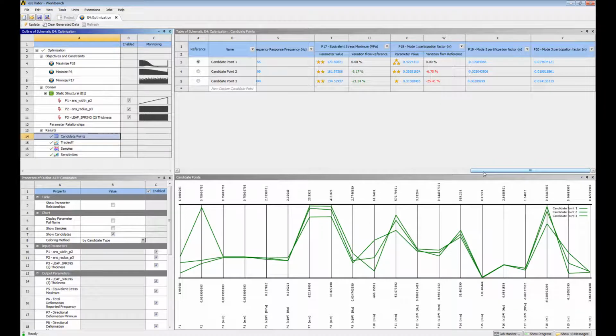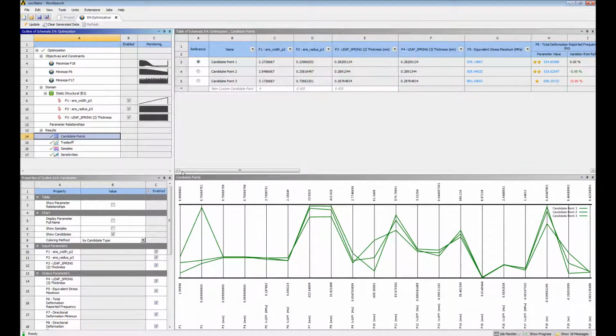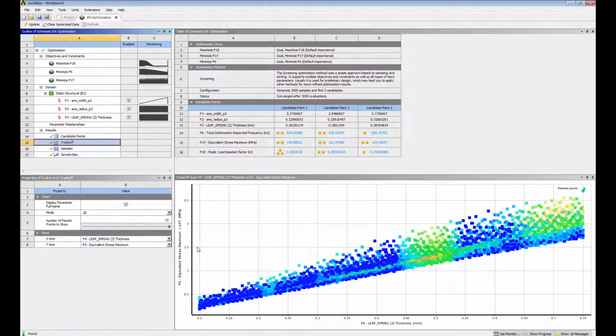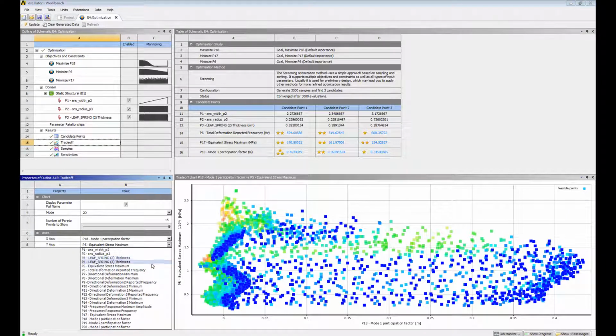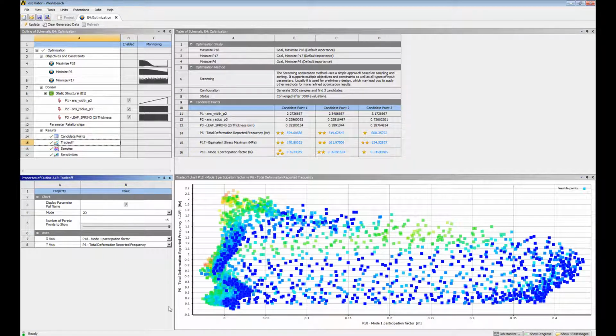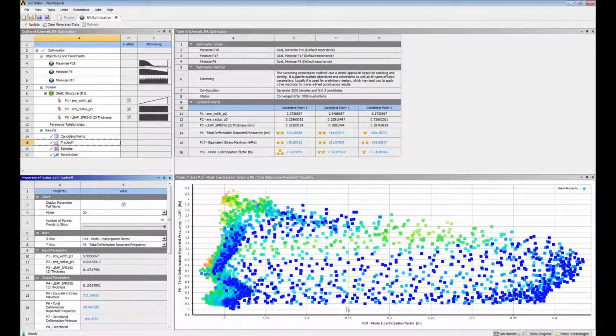So for example, in the trade-off study, I can plot a trade-off between participation factor, as well as the first resonant frequency. So this is my participation factor, and this is the first mode resonant frequency. If I want a low value with a high participation factor, then I'm looking at this particular set of lines. But you can see there's a wide spread. This trade-off study also shows me that anything within this block, this area, surrounded by my trade-off plot is possible. So I can find any given frequency, for example, 1 kilohertz. There are a series of designs at around 1 kilohertz, and I can click on any of these and get the design that would lead to that particular resonant frequency as well as participation factor.